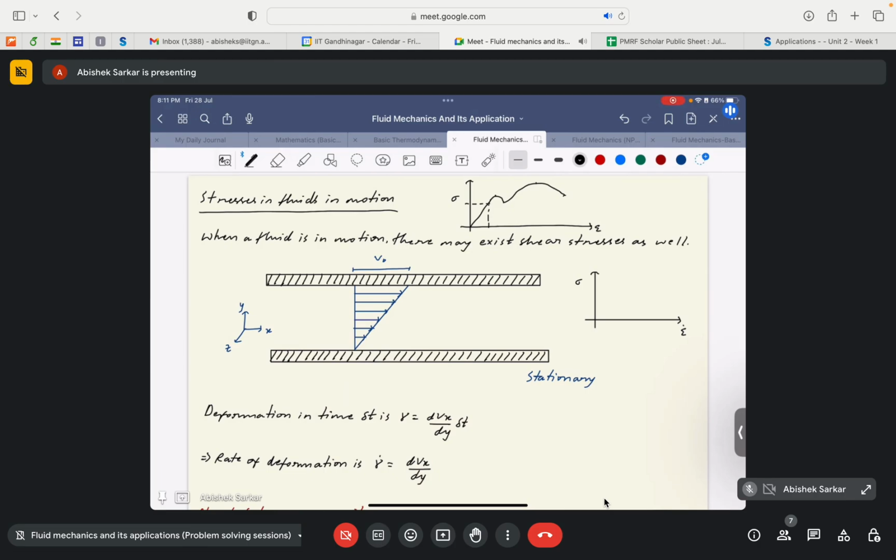Okay, instead of stress, it is the strain rate in the case of fluids. That is the difference that I wanted to emphasize between solids and fluids. I guess I was clear, and as you will eventually see, Newton's law of viscosity tells us that the stress in the fluid will be directly proportional to the strain rate, and there is no concept of any limit here.